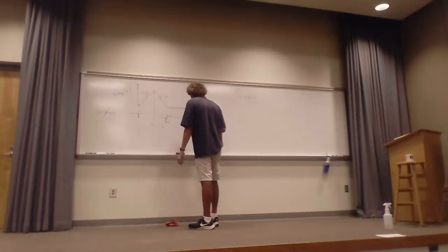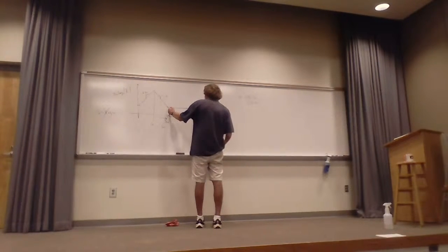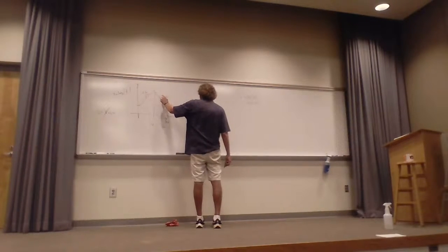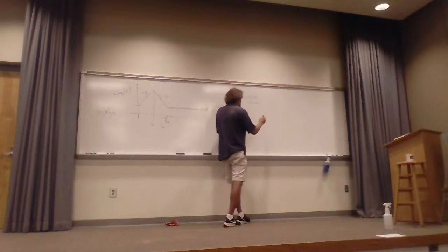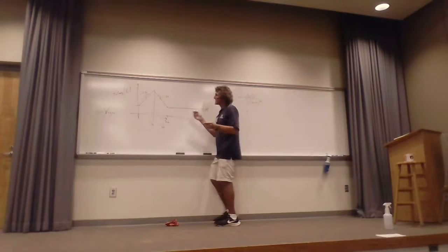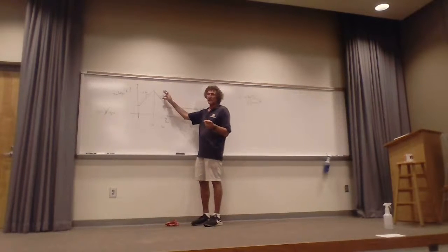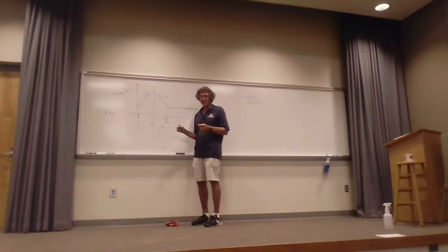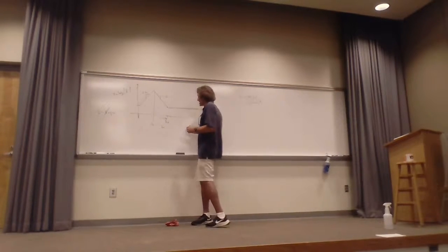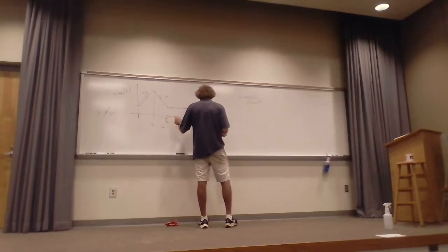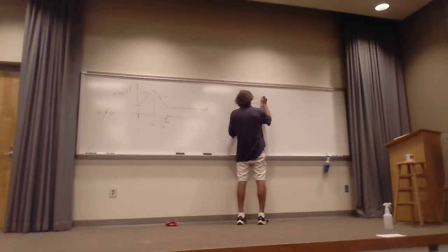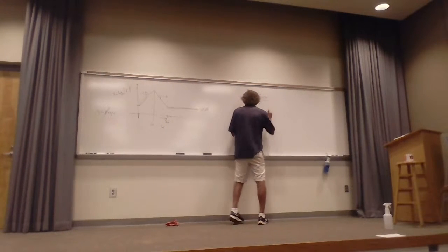And then when I take a look on here, there's another zero right here, correct, class? Mhm. I'm sorry, this is minus 20 dB. It was going up at 20, it's going down at 20, so this is actually squared, my bad on that one. Because just 20 would flatten it. It has to be S plus 10 quantity squared. Follow me? Because now it's going down. Then it flattens out here, and that's a zero. So it's S plus 30 here. And that's Z.